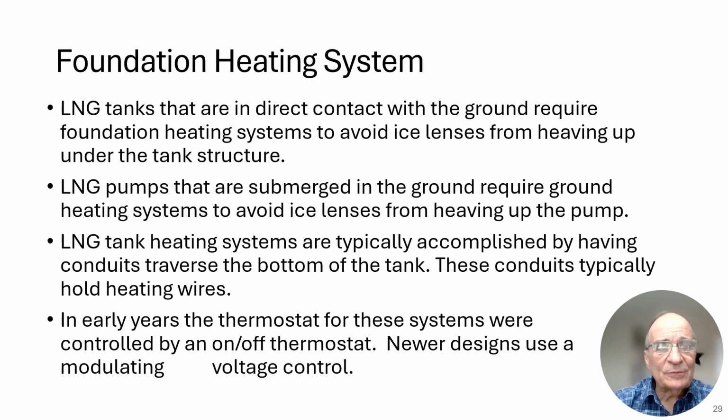Foundation heating systems. LNG tanks that are in direct contact with the ground require a foundation heating system to avoid ice lenses from heaving up under the tank structure. LNG pumps that are submerged in the ground require ground heating systems around them to avoid ice lenses from heaving the pump up out of the ground.